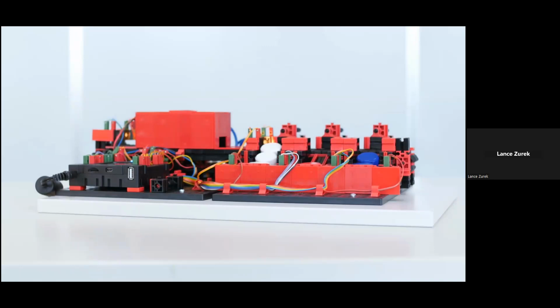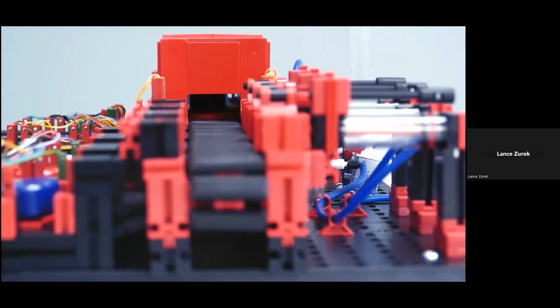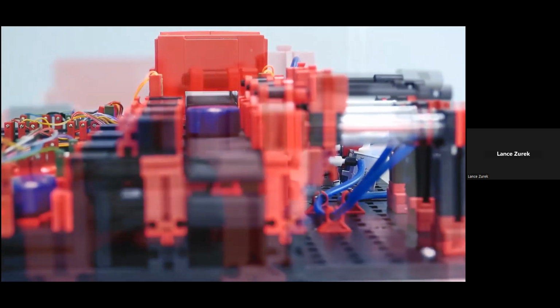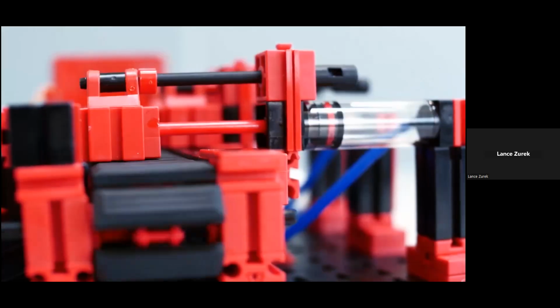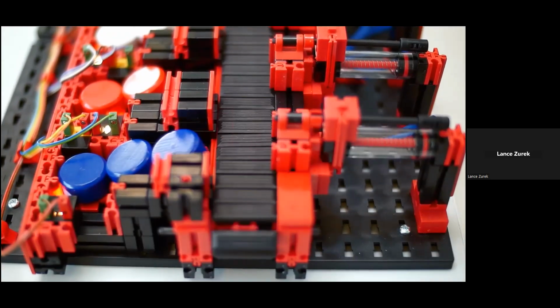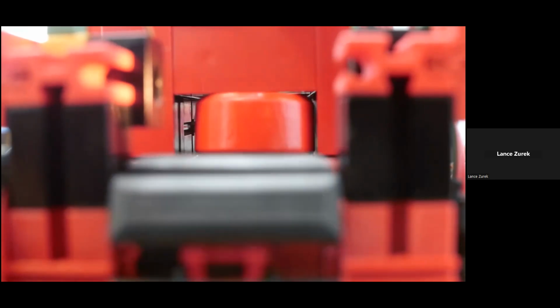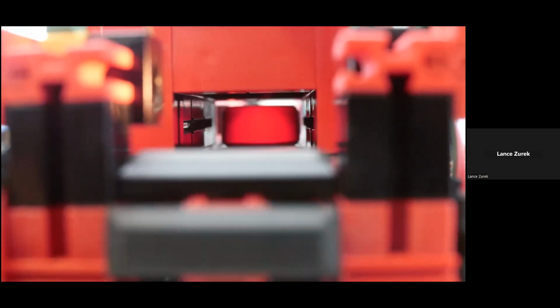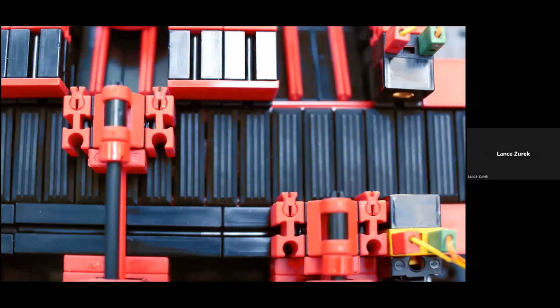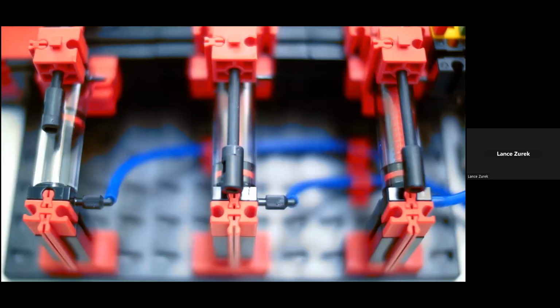Now, as with the models we've looked at before, the standard 24-volt version has the relay board for motor polarity reversal, again, multi-pin connector, 34 pins with a grid of 2.54 millimeters, as well as additional PCB terminals with push-in connections for all inputs and outputs. And again, you need to provide the PLC and the programming. And the limited edition 9-volt version, again, will come pre-wired to the pre-programmed robotics TXT controller, and one 120-volt power adapter is required with that.